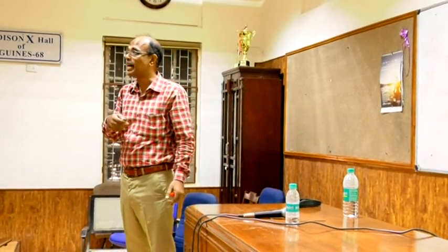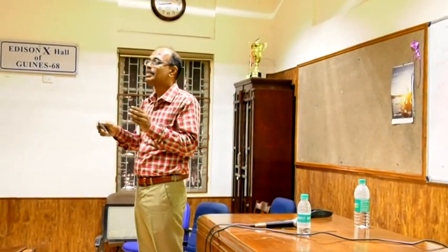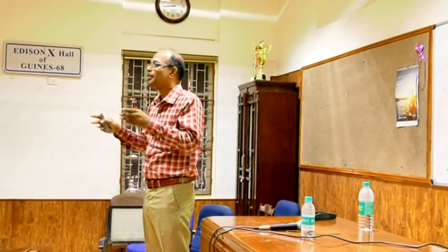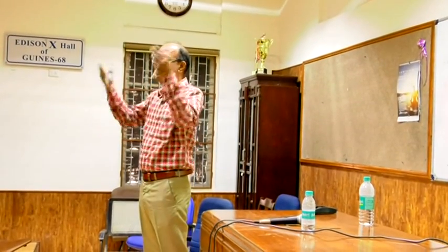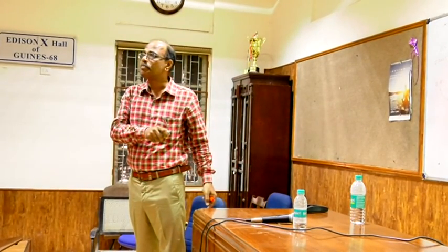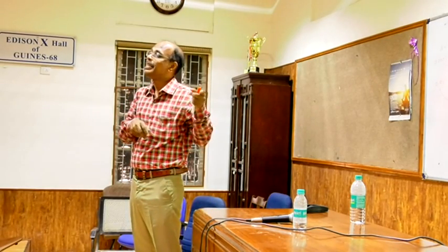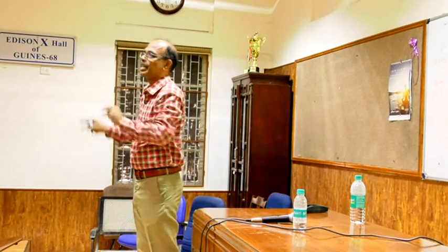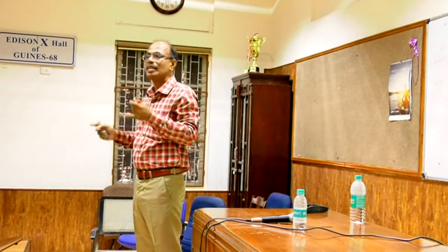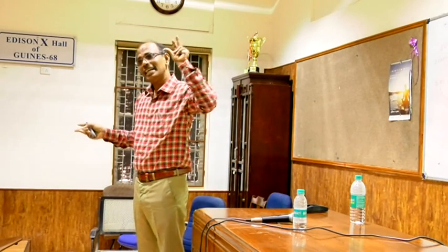With these assumptions, the Jacobian matrix can be further simplified into this form, that is B prime and B double prime. B prime is nothing but the negative of the imaginary part of the Y-bus matrix. So already we have the Y-bus matrix. From that we can pick the elements and, without any calculations, form these B prime and B double prime matrices. Once these two are formed, they can be inverted and permanently stored in the computer. During the solution process, we need not form B prime and B double prime, and we need not find the inverse, so it is readily available.